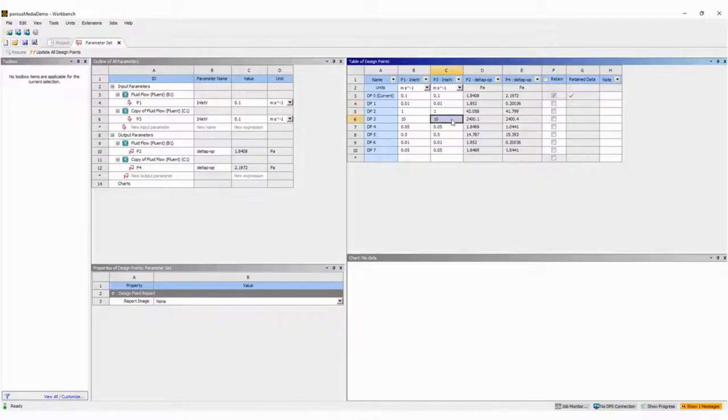Or get rid of the 10 here, so that we're not trying to span quite so many orders of magnitude. But this gives you hopefully some idea that if we want to match the flow rates from 0.1 meter, so 10 centimeters per second, to 10 meters per second, we're doing a pretty good job of matching the pressure drop to flow rates. And you can now run a simulation that's many orders of magnitude faster by using this type of porous media